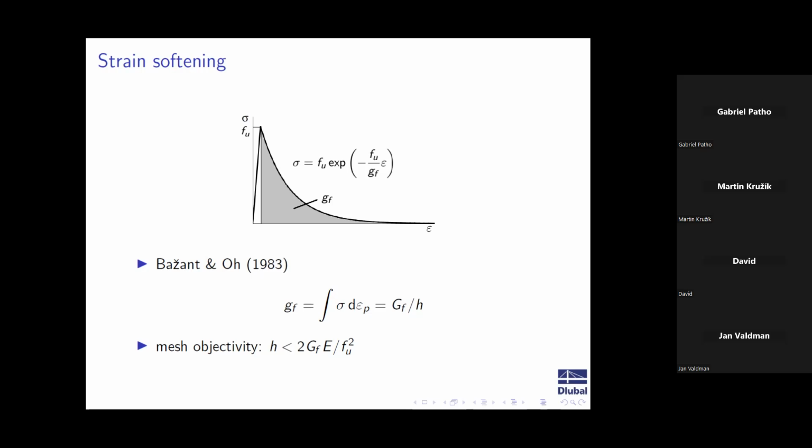So I have some inelastic work under the graph, and this is an exponential strain softening for my equivalent plastic strain, which drives hardening, in this case softening. So the behavior of the yield surface.